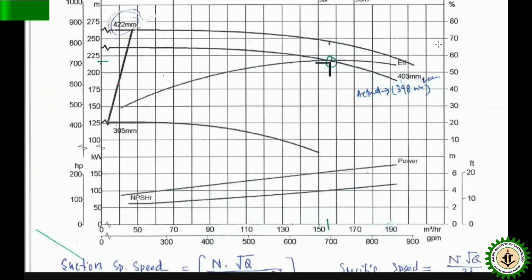You have to navigate the operating point in between the surge and choke to avoid any damage in the compressor. Same for compression, as it is a compressible fluid. Pump, as I said, is an incompressible fluid. The same thing is valid for other machines like blowers, which also have performance curves. So this way you have to analyze.